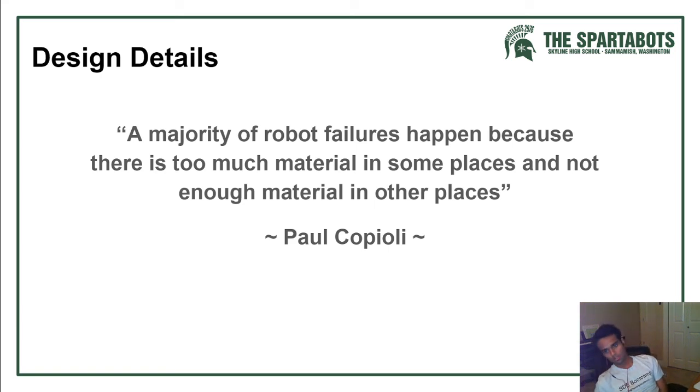So a major failure point is when there's too much material in some places and not enough material in others. So in places where you think there is not enough support, don't be afraid to reinforce it. But at the same time, if it's like a gearbox, you don't need to pocket it to be like a quarter of an inch. You can definitely get away with 0.15 pockets. So just keep that in mind.